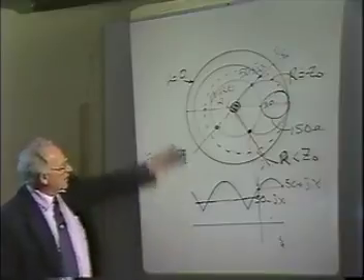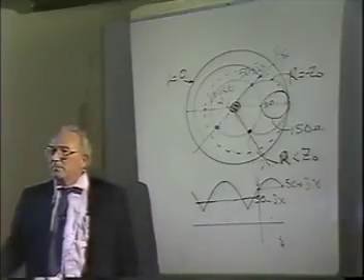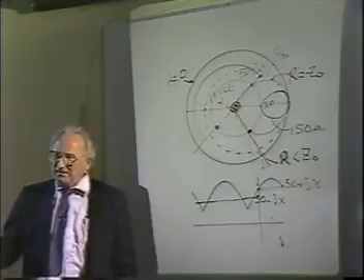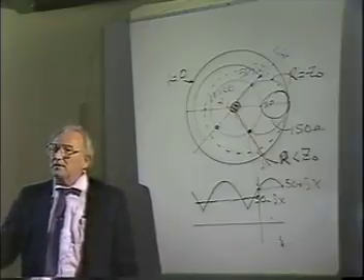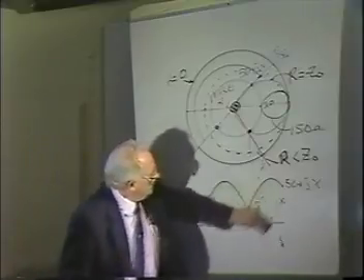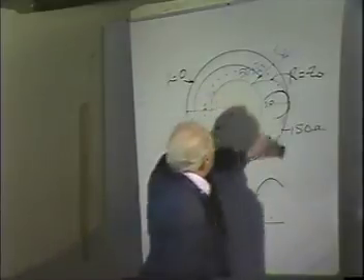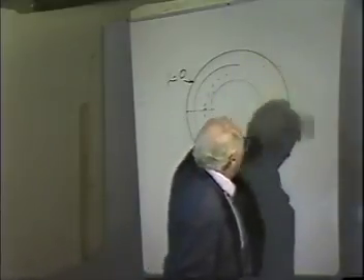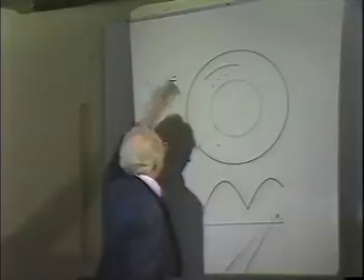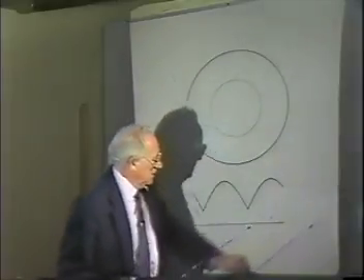One is, where does the power go? And the other is from a circuit element standpoint. Minus JX cancels plus JX. Power-wise, you're directing the power. You're phasing it so that the power goes in one direction. One thing is pretty definite, though, it takes a 1.1 to cancel a 1.1. It takes a 2.0 to cancel a 2.0, and so forth.